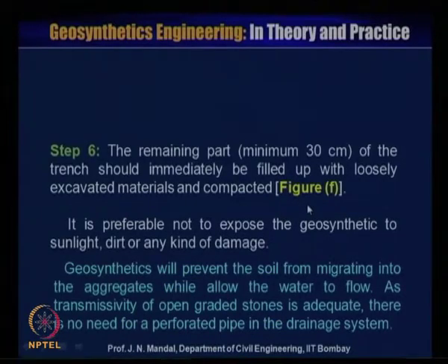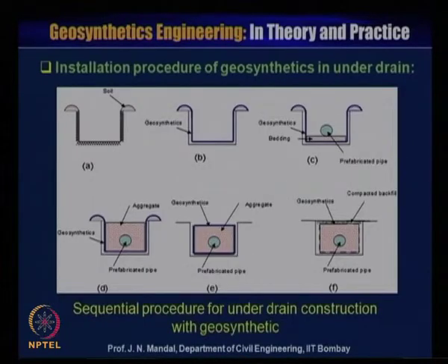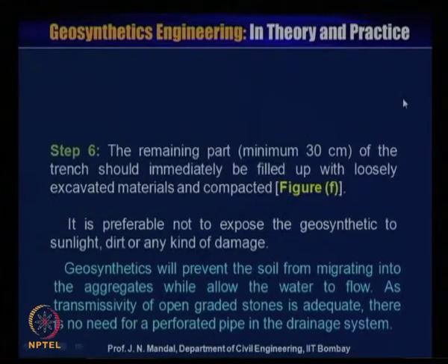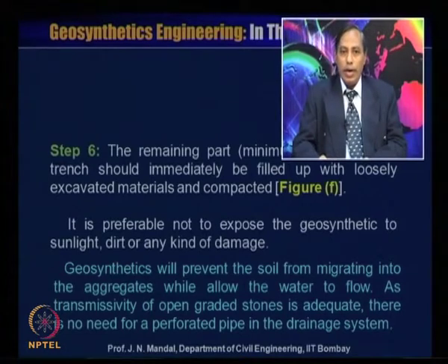Then the remaining minimum 30 centimeters of the trench should immediately be filled with loosely excavated material and compacted. So, here this loose soil is on the top. It is preferable not to expose the geosynthetics to sunlight, dirt or any kind of damage.